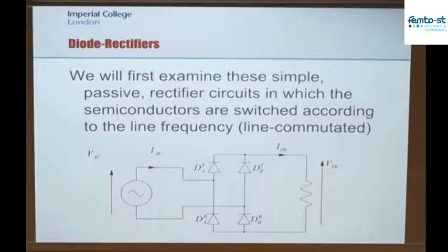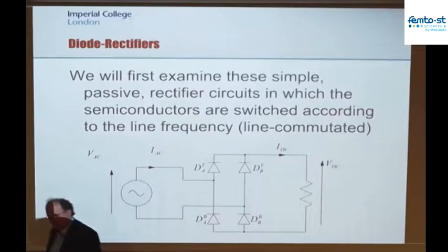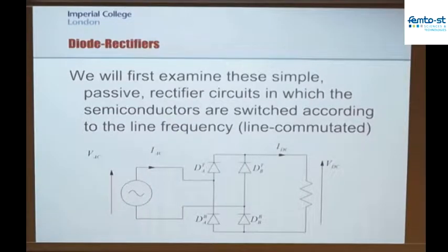But I will talk briefly now about rectification, and then we'll talk a little bit more specifically about some circuits specifically for energy harvesting. So rectification, this is a circuit that you are probably very, very familiar with. As I mentioned, it's of limited use for lots of energy harvesting approaches because the voltage that you typically get from your transducer may be very low. You won't be able to pull these diodes into conduction easily enough. And so we've got to think probably about better solutions to doing AC to DC conversion than this circuit. But it's a very well-known circuit.